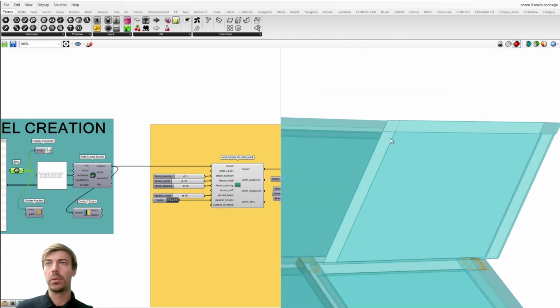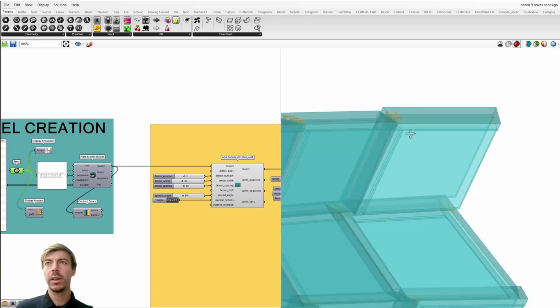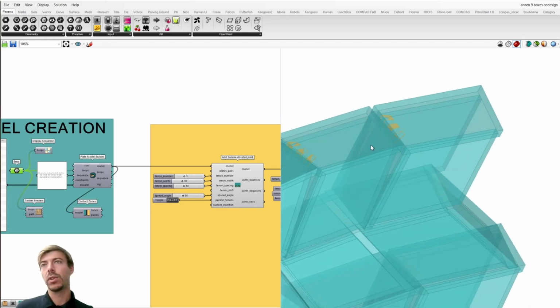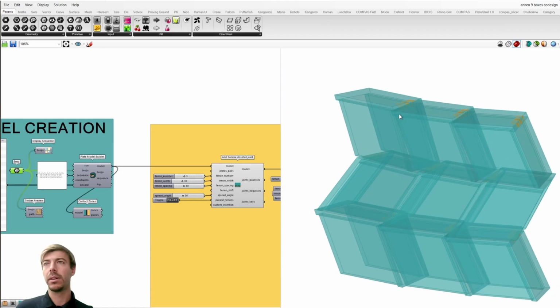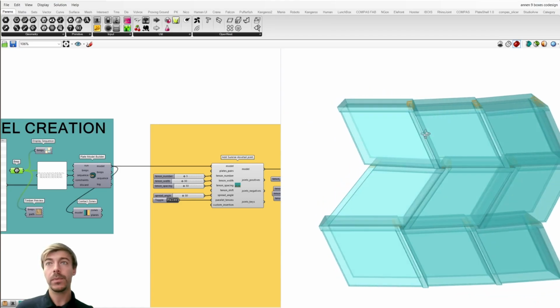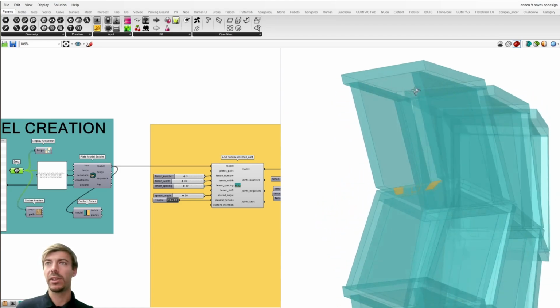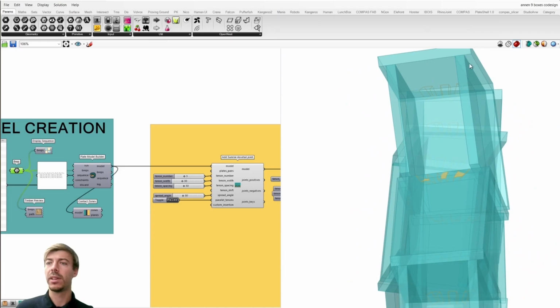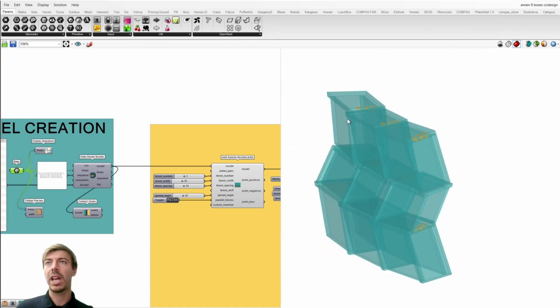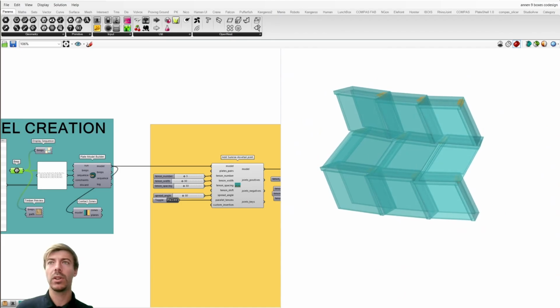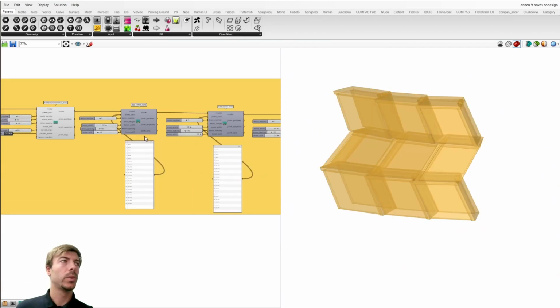So when the two plates here you see in Rhino, we have one coming at the edge of the top plate of this box. And so this type of joint can only be applied for that configuration of plates. For the other plates, which are not on the edge as you see here, we need to compute another type of joint. And in that case, we will choose the through tenon joint, which is a classical one.